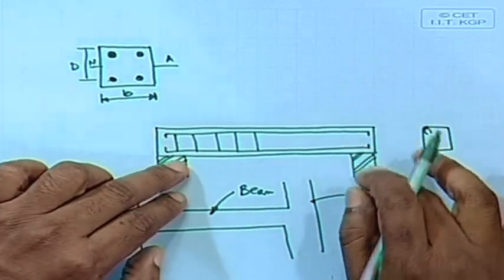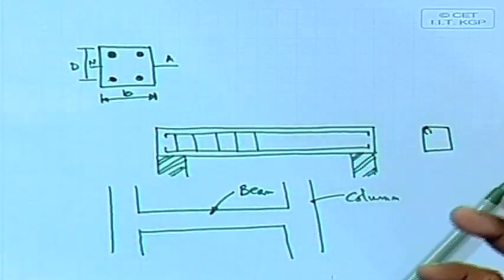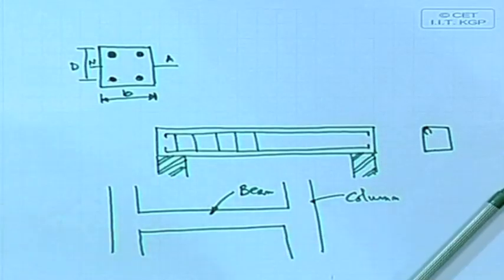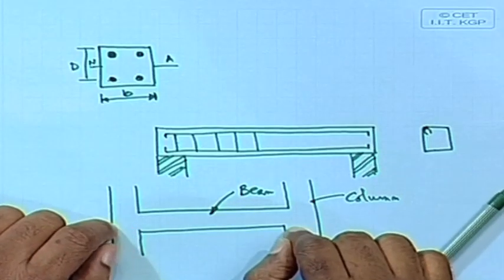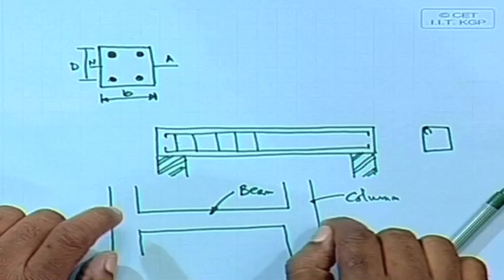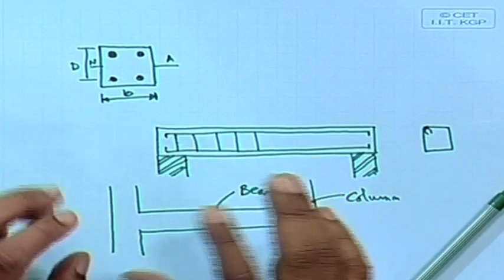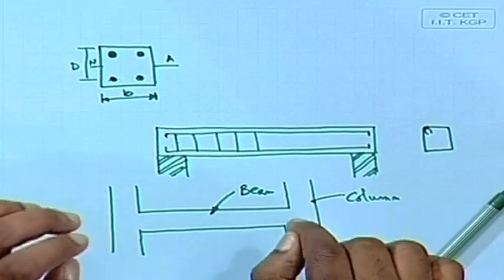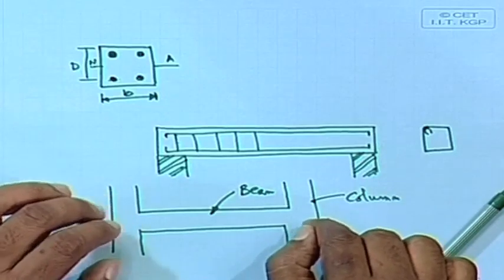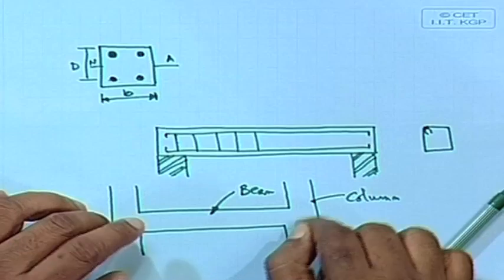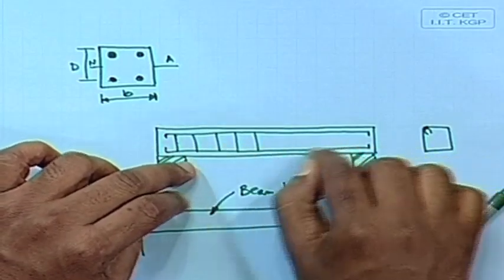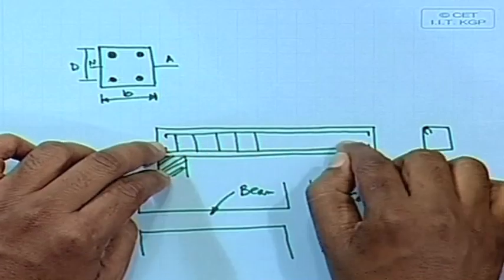In this case, you are simply placing the beam on top of the wall, whereas here you are fixing it as if it is clamped. I can consider this as a fixed case. So, that means moment will be developed at the two supports. So, you have to provide reinforcement in both supports, that means you have to design for the support moments also. Whereas, in this case we have to design only for the span moment, because that is the only moment developed in this particular case.